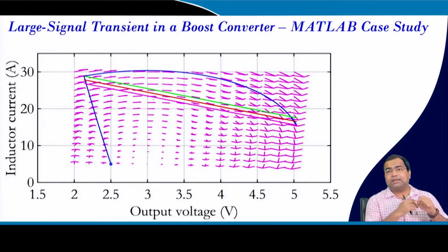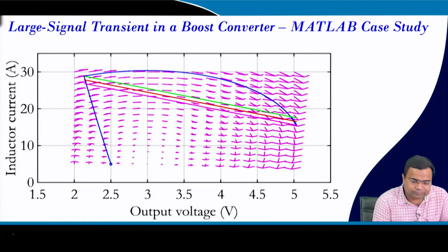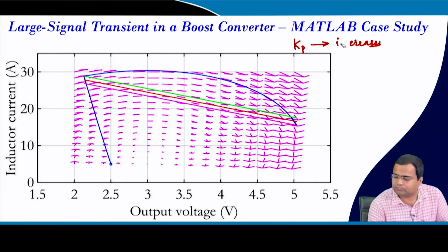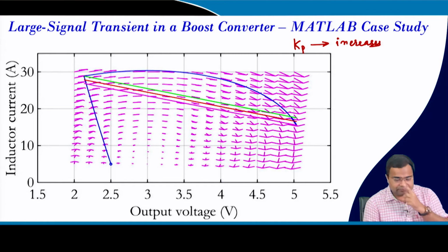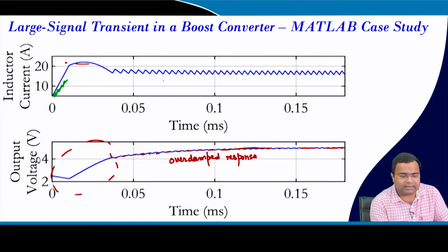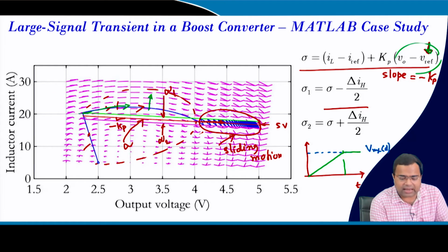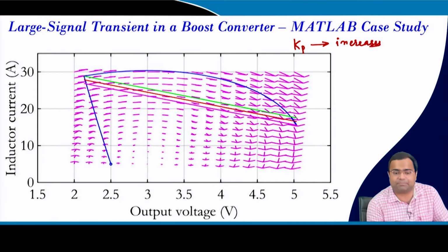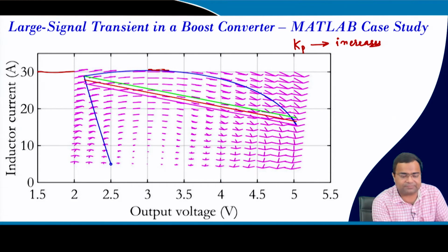Now, imagine if we can increase this slope. So, what we did now, we have increased the slope, Kp. If we increase the slope, then you see the current overshoot has increased, because if you go back to the previous slide, the current overshoot was around 22 ampere, not very high, but here it goes up to around 30 ampere, this is my current, right.